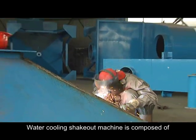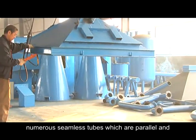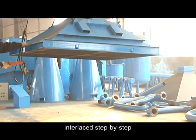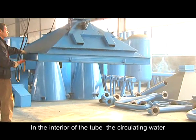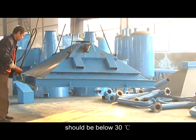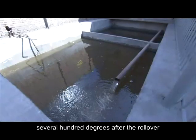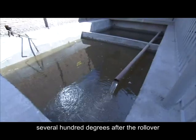Water cooling shakeout machine is composed of numerous seamless tubes which are parallel and interlaced step by step. In the interior of the tube, the circulating water should be below 30 Celsius degree. It is mainly used for the sand cooling above several hundred degrees after the rollover.